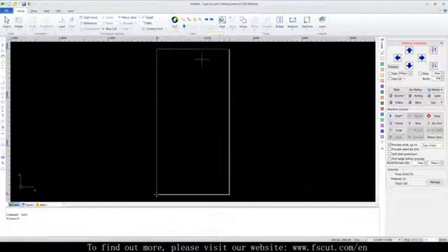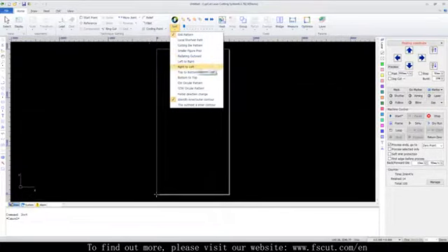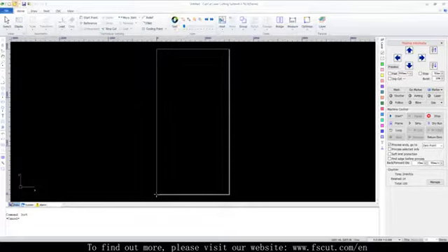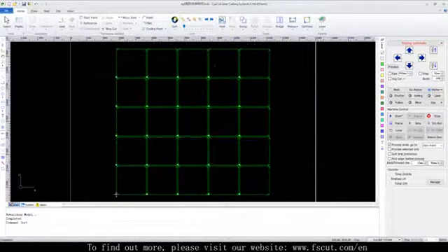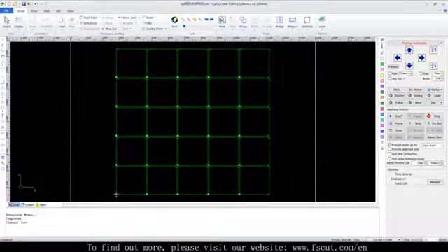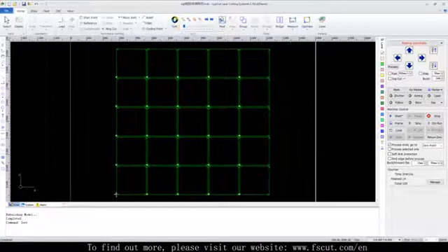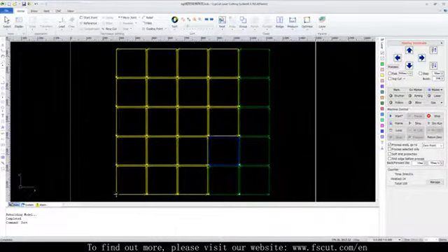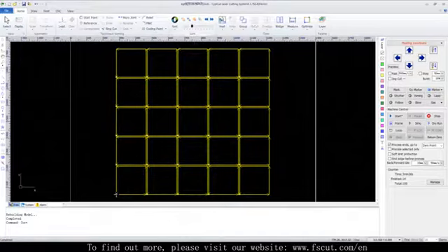Left, right, top, bottom. These four types are mainly used for cutting well-arranged graphics. For instance, the square matrix, select them, choose the left to right. And we can drag this progress bar to simulate the cutting path. For this we can get parts cut within rather regular and short travel path. However, there would be too many unnecessary travel paths.